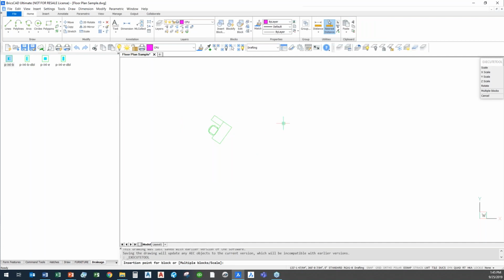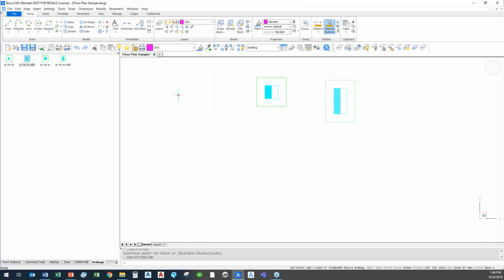And then it's easy to just go in and bring in, see, there's my B inlet, my double B inlet, oops, sorry, I didn't click on it, double B inlet, right? My E-based inlet. So all of these symbols can just easily be brought in on the correct layers, adjusting rotations and scales and whatever I need. So it's a very easy way to be able to bring in and handle multiple structures.